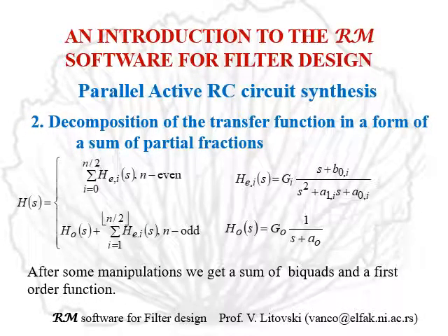Of course, since the poles are complex numbers, which have conjugate counterparts, by putting together the conjugate pairs, we transform the transfer function into one containing two types of summands. One is second order and the other is first order.